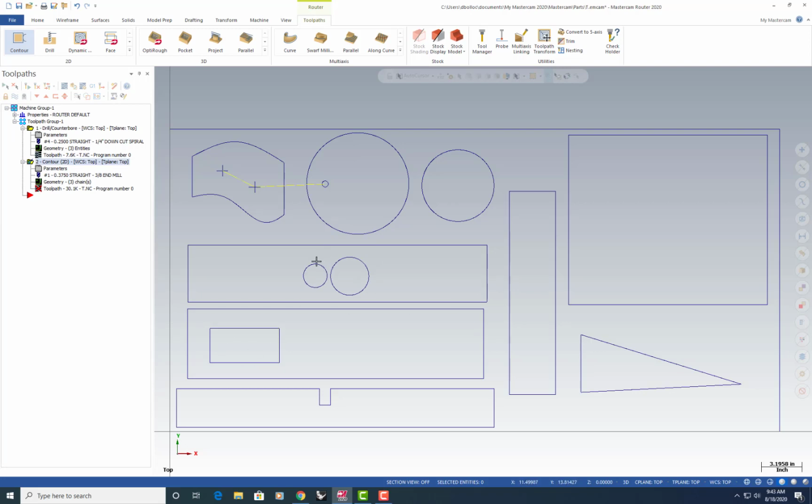But it doesn't show me my blue lines here, and it's got a red X here. So anytime that you change anything on your toolpaths, your bits, your add geometry, the direction of cut, it needs to regenerate those toolpaths. So in order to regenerate them, you hit this red X here, and it regenerates, called dirty operations. And now you notice it has those 3 parts cut out.